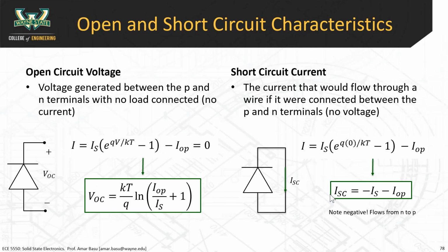All right. So from a circuit standpoint, we're getting at how you actually extract energy from this thing. There are 2 characteristics that we first have to be able to calculate: the open circuit voltage and the short circuit current. These are both pretty straightforward to do. The open circuit voltage is defined as follows: if you had a diode that wasn't connected to anything, and you shine light on the diode, what is the voltage that would be generated between the 2 terminals?